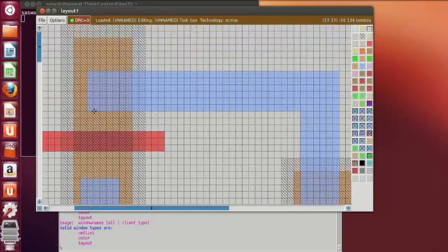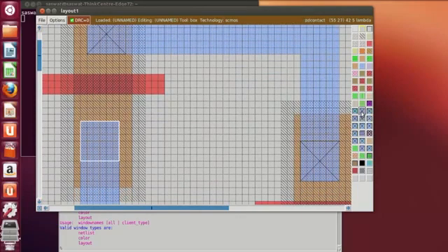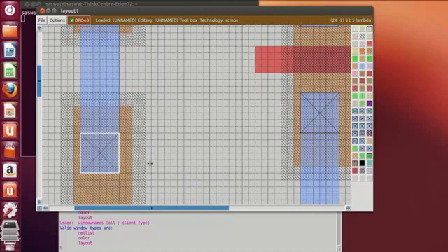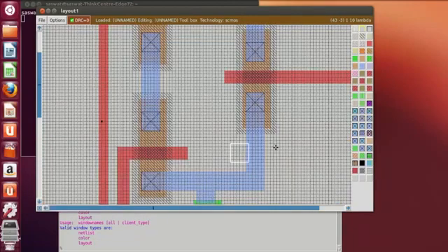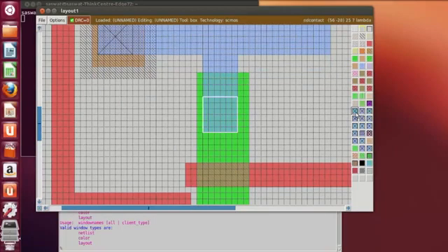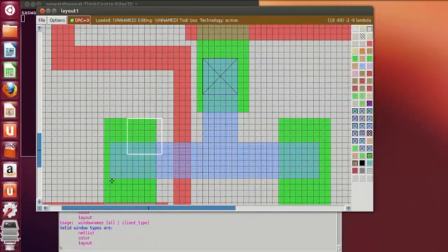Now this is VDD, so this is a PD contact. Here also we have the PD contact, PD contact, PD contact over here also. Okay, after placing the PD contacts, we have to place the ND contact. So middle click on ND contact, then over here also the ND contact, ND contact.